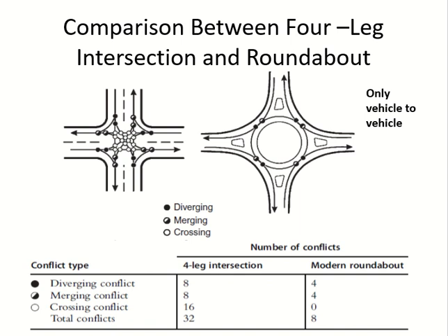You have to put a sign or a signal to eliminate them, but by default, all of them are open. You can have merge, you can have diverge, you can have crossing. All of them are open. But when you put a roundabout in the middle of the intersection, you eliminate all of which type? Crossings. All crossings are eliminated from all directions. Okay, so crossings become 0.